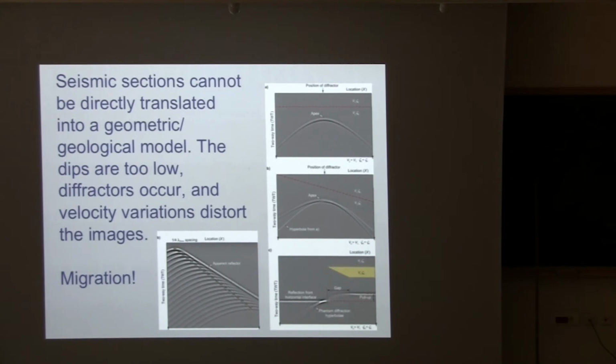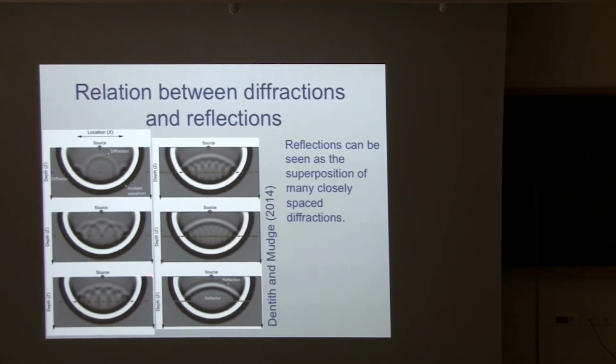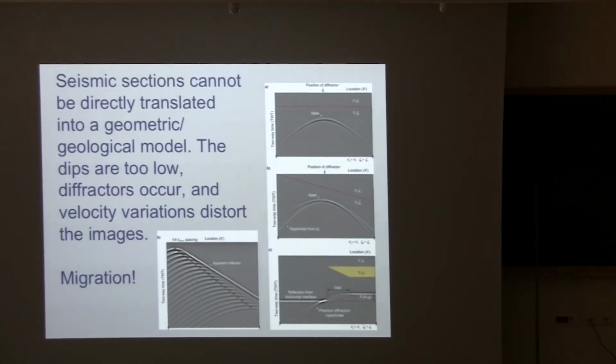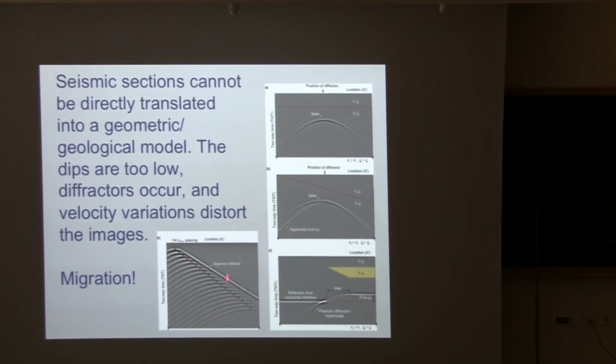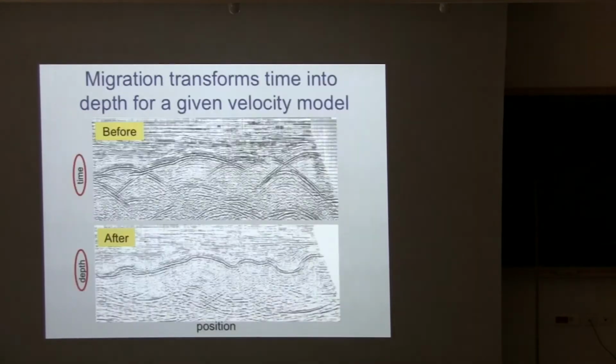Seismic modeling and acquisition is quite complicated. You cannot just use the time at which your energy is coming back to the surface. You need to do what's called migration. Migration will replace all your measured section, your time section, in space. Otherwise, your depth and geometry will not be really correct.